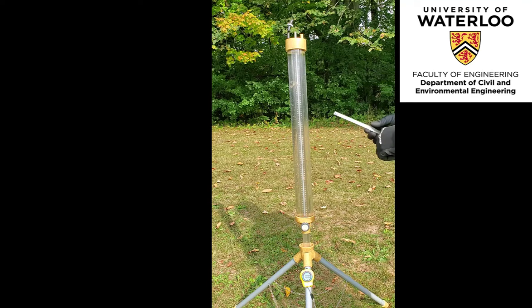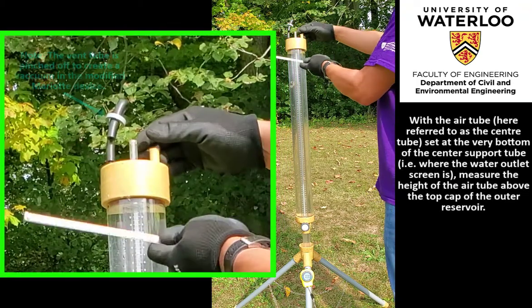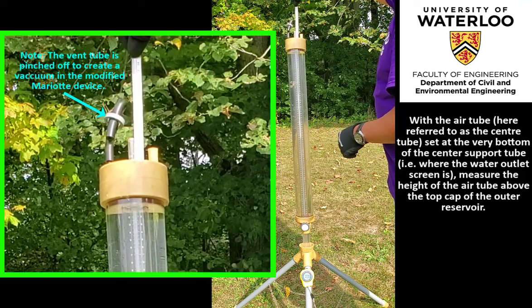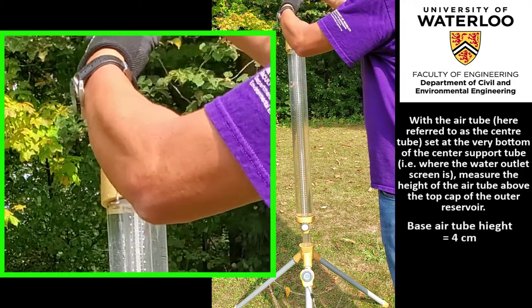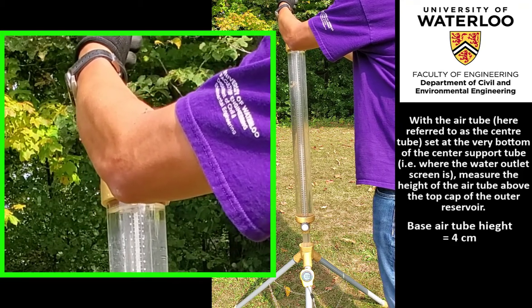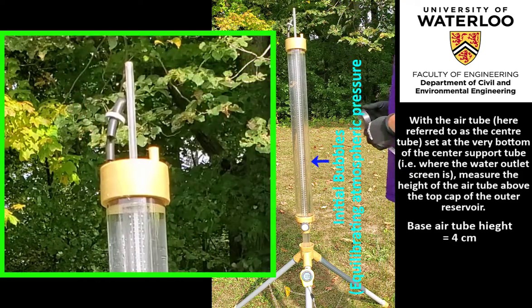Okay, so the first step we're going to do is raise up the center tube, which controls the height of the water inside the well, and that's usually done at 5 or 10 centimeter intervals. So we'll measure from the top, which is about, start initially at 4 centimeters. So we'll raise that up to 14 centimeters.